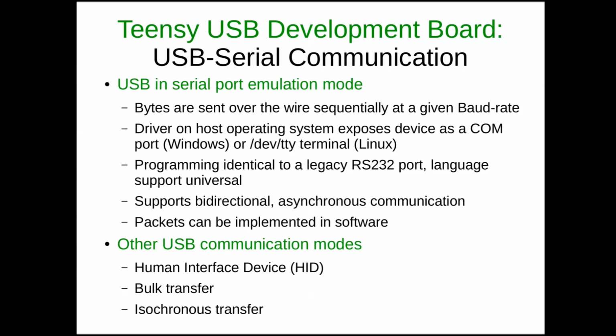Finally, we have isochronous transfer. Isochronous transfer is what a typical USB audio device is going to use. The idea behind this mode of transfer is that when data gets lost, like let's say you're listening to some music on your USB headphones, if you were to drop a few bytes of information there, you may hear that as a little blip on the song that you're listening to, but you don't want that data to be retransmitted at a later time.